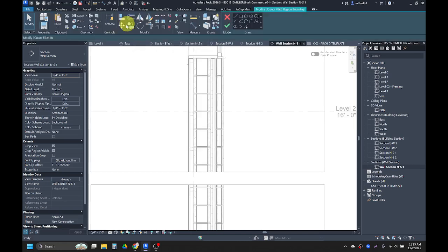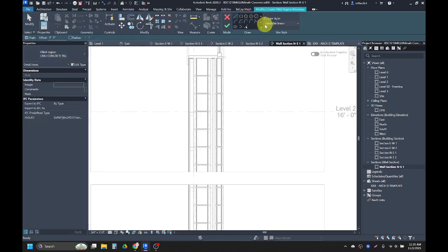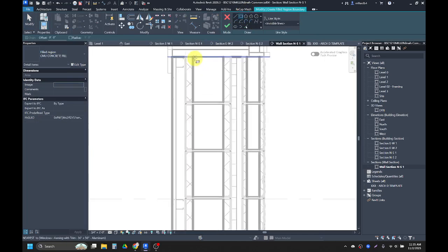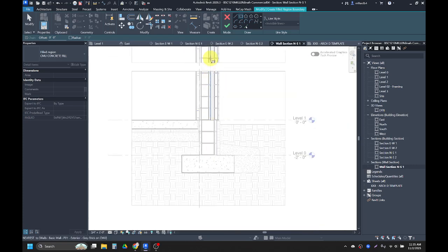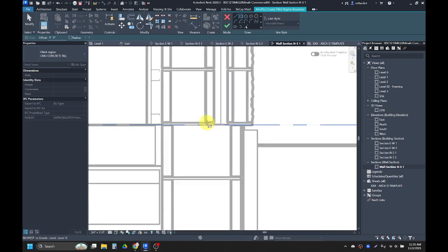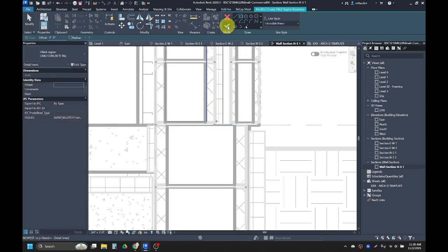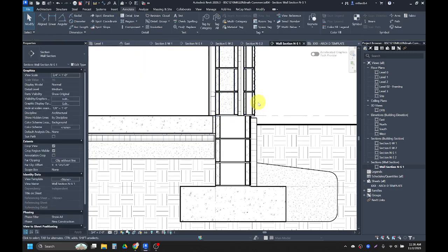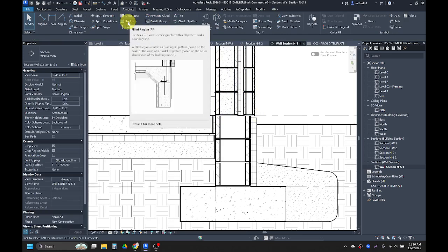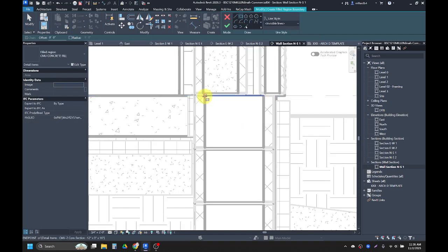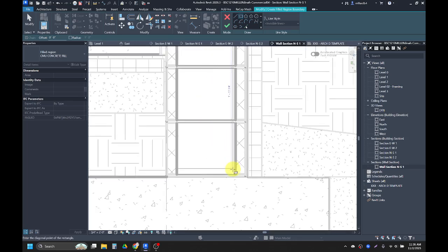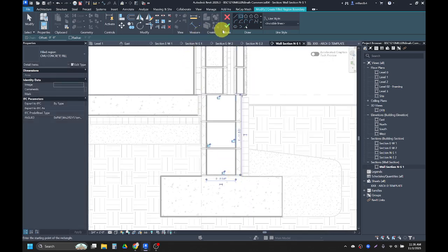And then another region with my concrete CMU fill, an invisible line, rectangle from underneath my window. And this one I'm going to carry all the way through to the other view even. Green check. Hit escape a couple times. And then last one of these, I'll do a region. Click on my little rectangle. All my settings are still the same. Just inside here, and then green check.